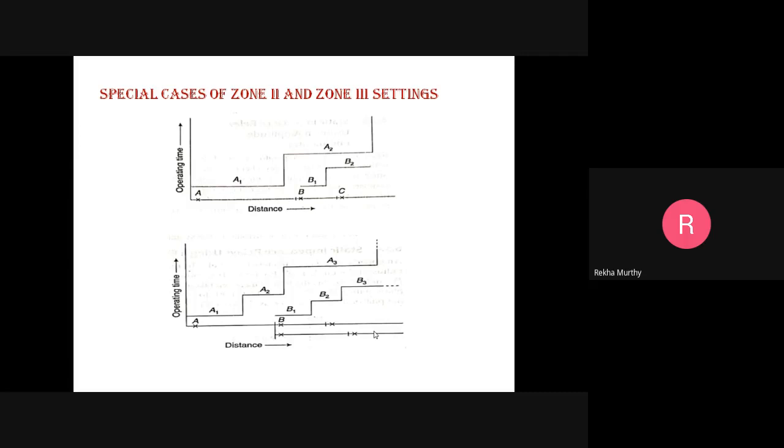So in order to overcome this, this is achieved with the additional time delay, which you can see here, the third zone adjustment with an additional time. Instead of increasing it here, we have taken 50% of it initially, then later on another 50%. Then further we have covered the entire region of B, that is B1, B2, B3. So the entire 3 zones have been covered under the 1 unit. Okay, so that is what has been completed in the zone 3 sessions.